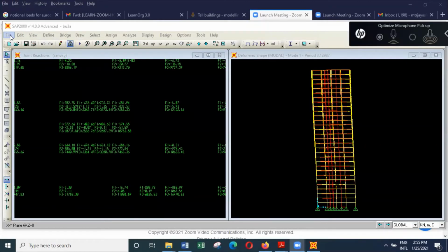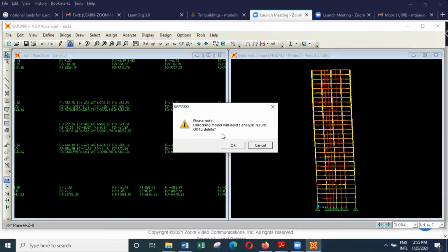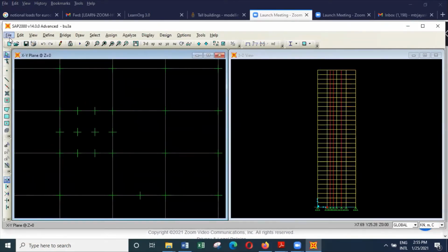So we'll move to open. So if you are having loads in excess of 12,000, the piles may need a capacity like 12,000 divided by 4 is 3,000. So with the self weight of the pile and pile caps and all that, you will find that the pile loads can be around 3,500 kilonewtons. So 1 meter piles can easily take about 3,500 kilonewtons.